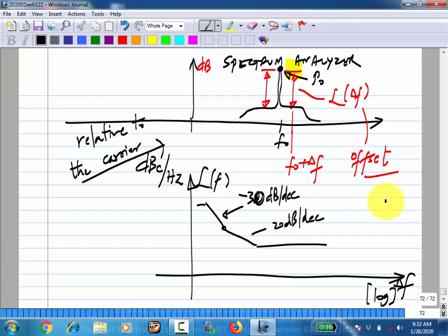So you will need to know those things. Now we know the very basics of random processes and how to describe a random signal. You can use the variance. We'll typically consider only zero mean, so that is okay. To see how rapidly or slowly it's varying, you can use the autocorrelation and spectral density. Most often you will have the power spectral density and you integrate that to get the variance, the standard deviation and so on.